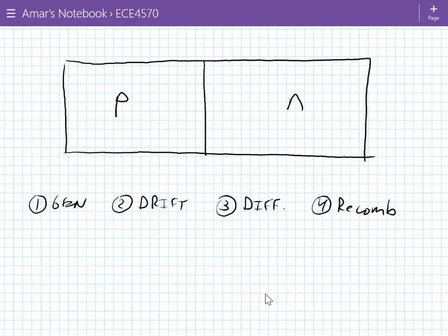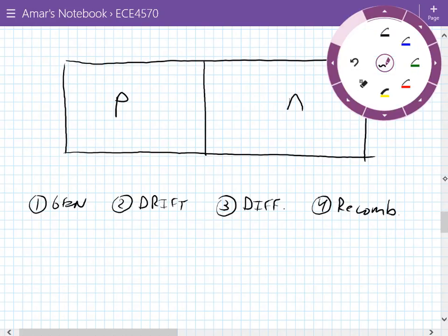Where's the concentration gradient here? Between the whole thing, yes. So let's talk about specifically, if we're talking about holes, which one has a higher concentration of holes? Yeah. So the p-type material has a high concentration of holes. The n-type material has a very low concentration of holes. So the holes are going to diffuse from high to low concentration, right? So we've established that. That's the thing that drives it the most.